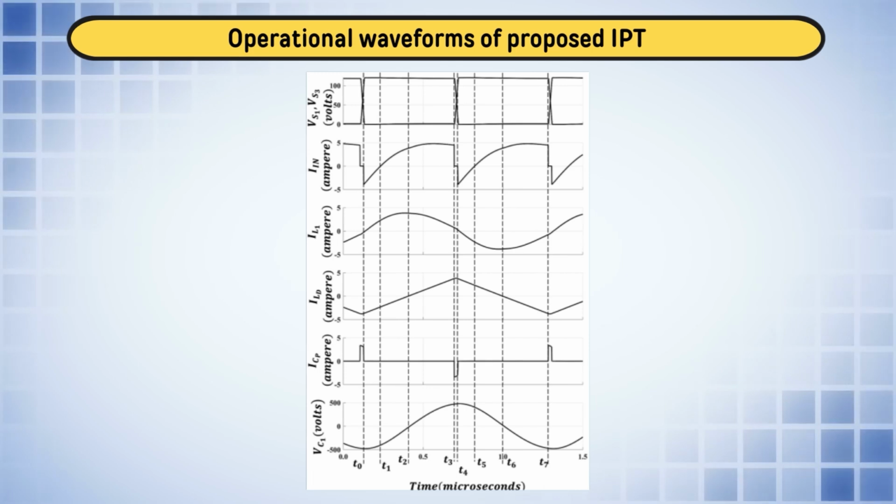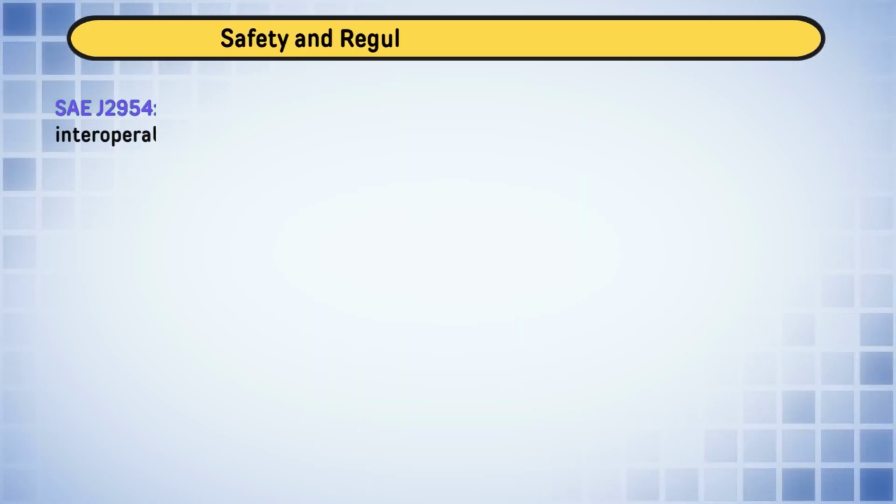On the primary side we have connected 2 transformer windings, and on the secondary side using 2 transformers we have made these Scott connections, and successfully the power is transferred between the DC input and the battery as well as from the battery to the input. Here we have given the modes of operation, how the converter is operating, how the switches are on.